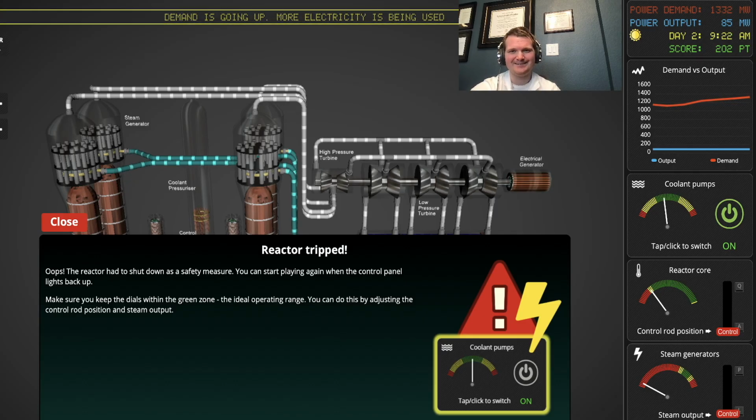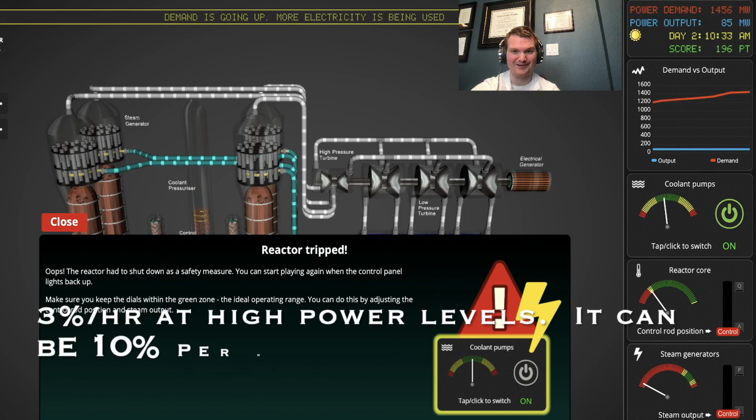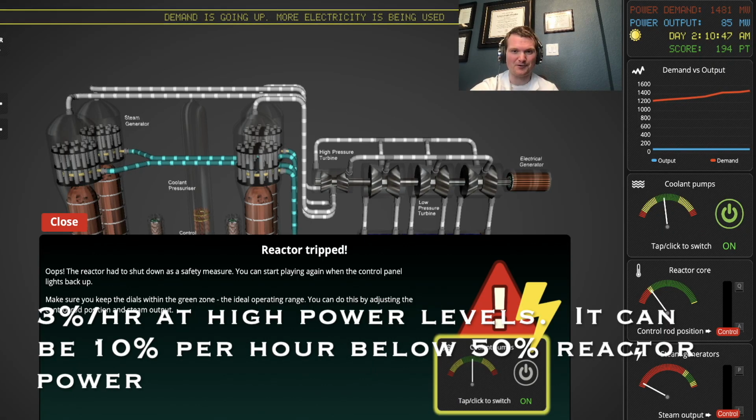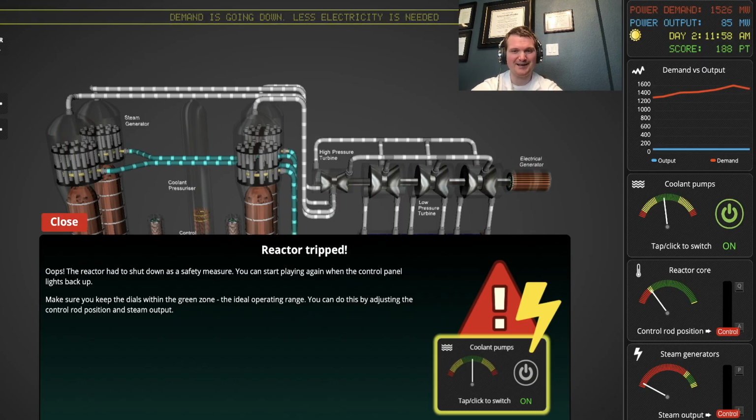And another thing is there are limits when you're above 50% power. The ramp rate limit can be as low as 3% per hour. So you'd never be able to move power this quickly. A full power ascension takes days. And there's also additional feed water pumps you would place in service. There's a whole bunch of other things, but again, for a simplification, this is pretty good.